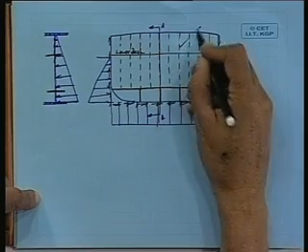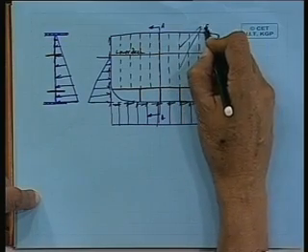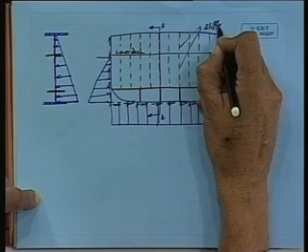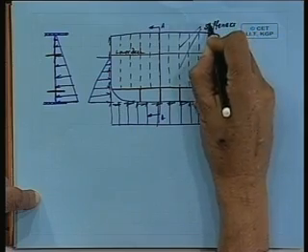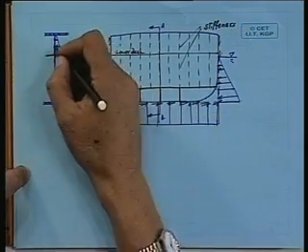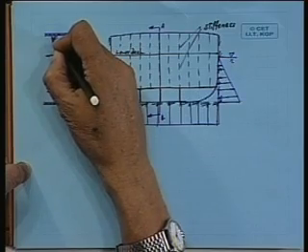Okay. So, this stiffener I can draw here. Considering the flooded condition of the bulkhead, the stresses generated due to the transverse load are much larger than whatever is imposed by the in-plane stresses. Okay.